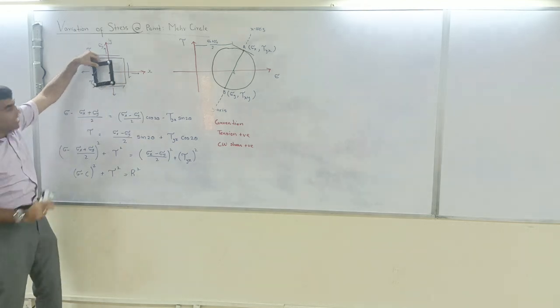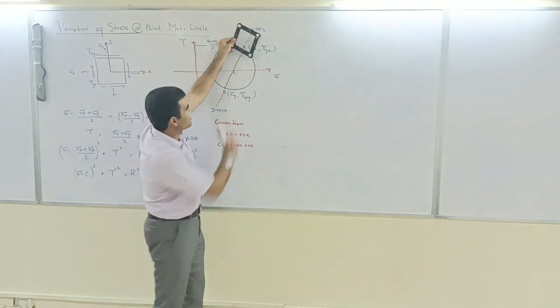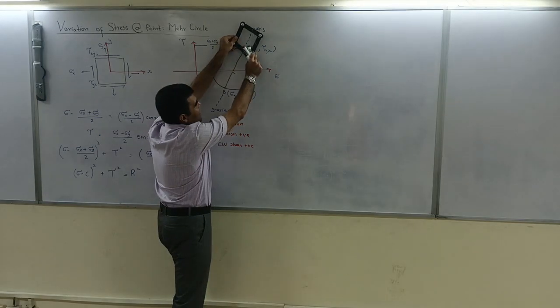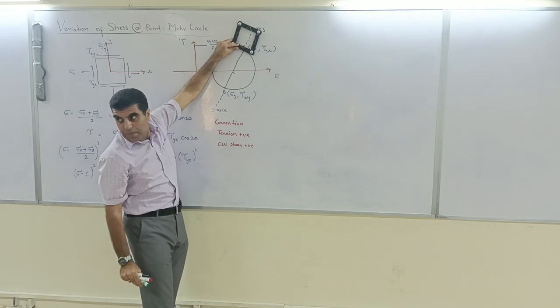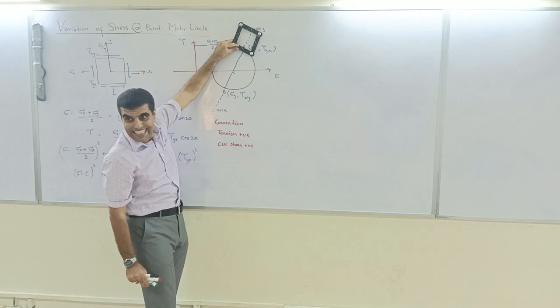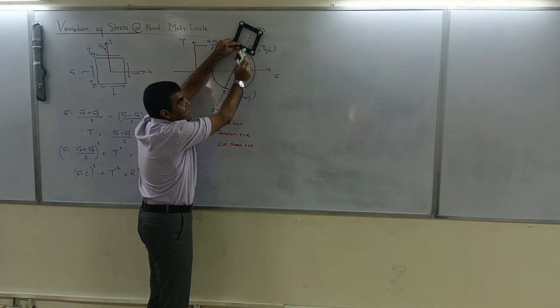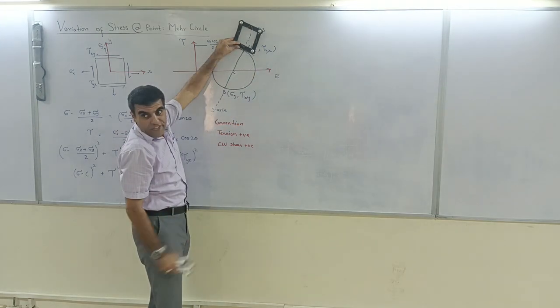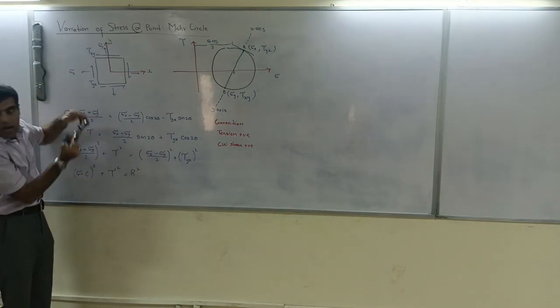The Mohr circle is telling you the orientation of this element, which looks like this. So this element is located like that according to the Mohr circle. Your radius is normal to the face. This is the face where you have the stress x and tau yx.